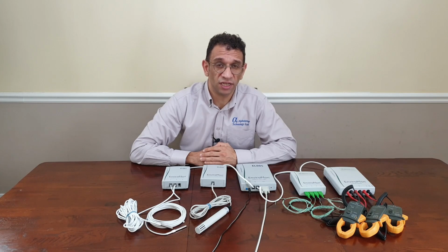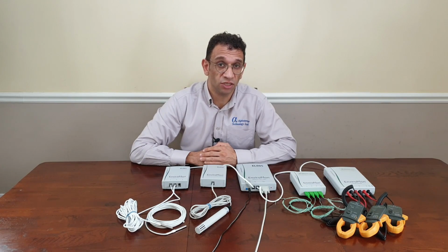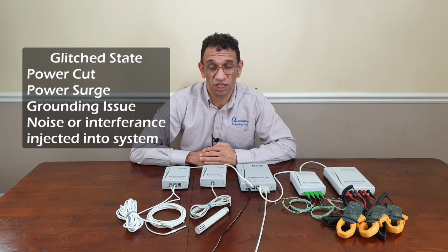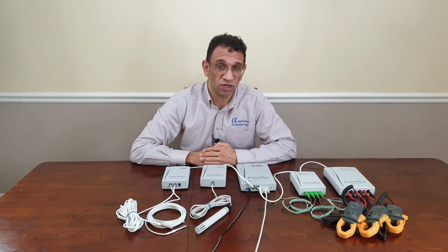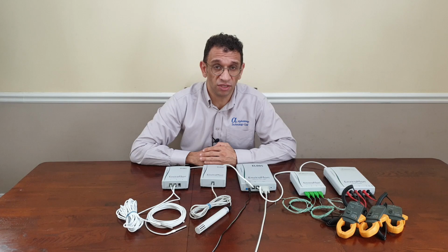Now sometimes the logger can get into a glitched state, which can cause some or all the readings to be blank. This can occur if there's a power cut, a power surge, or a grounding issue, or some kind of noise or interference being injected into the system. Sometimes just exiting the software and restarting it will fix the problem. Failing that, you can disconnect the converter cable or cables from the data logger and then connect them one at a time to see if everything appears again.